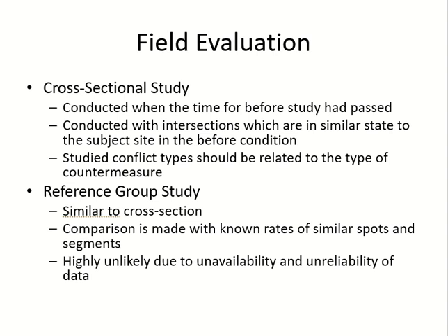Okay, in a cross-sectional study, you didn't do a before study. You made some changes on your site, but before you made the change, you did not do any conflict study. So you only have the after data. No before data is available. Then you can do a cross-section study. So what are we comparing? Our site after and other sites which are still in the before condition.